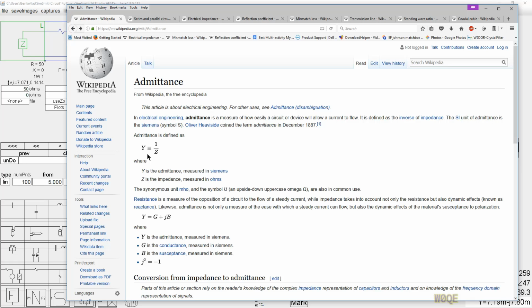So if you convert from impedance to admittance beforehand, which is a fairly simple thing, it takes a little bit of math, but it's algebra, and then you just add the 2 admittances together, you've got the answer. Then you can take that number and convert it back to an impedance because it's just 1 over that number. So a lot of times, doing the problem by hand, it was more convenient to have admittances than impedances during the problem.